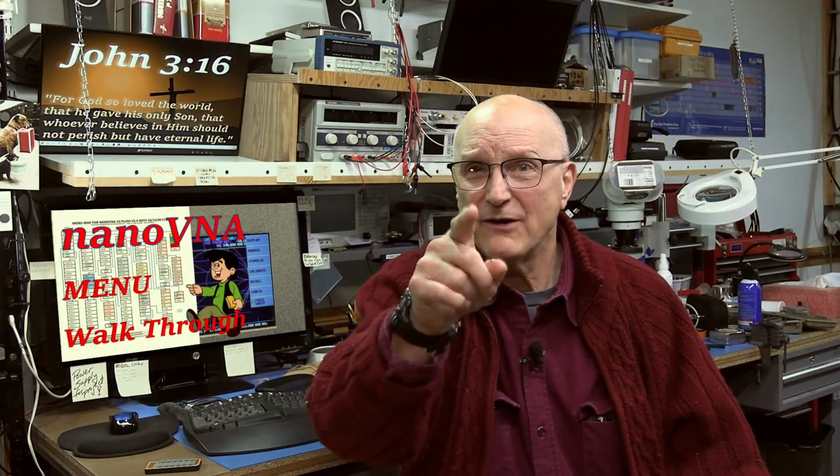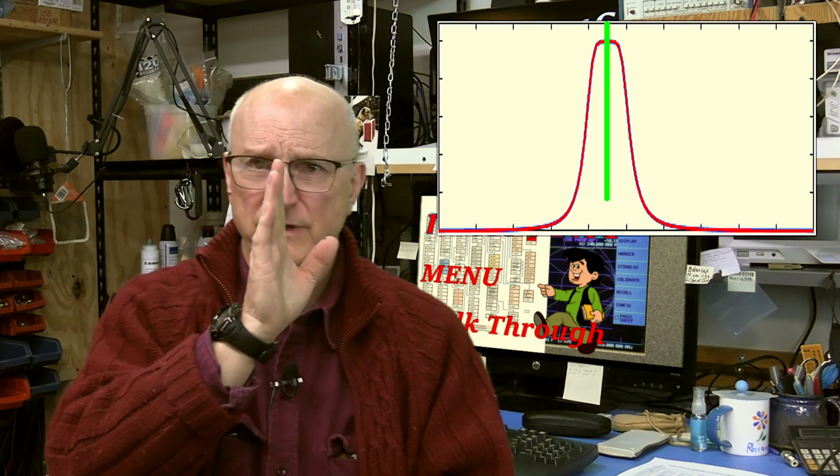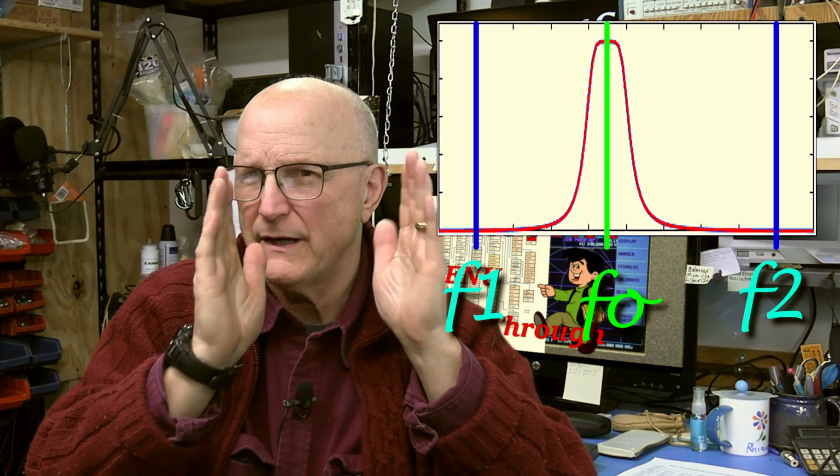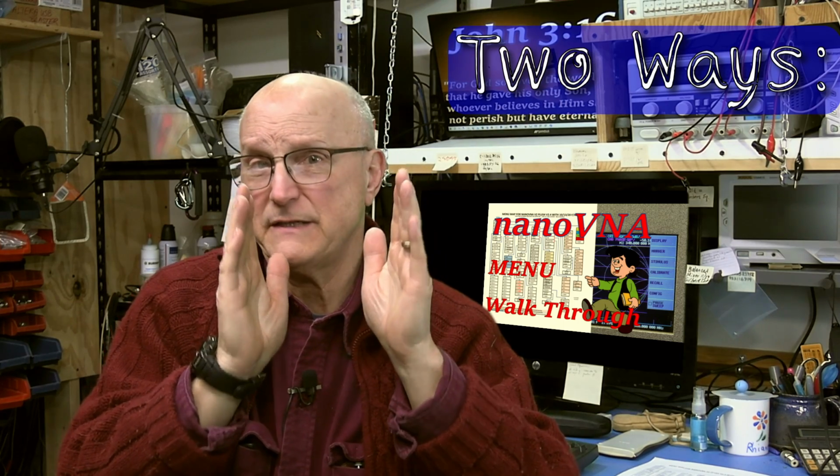But there's a second way to do this. So suppose that I wanted to test a bandpass filter. I know the center frequency of the filter, and I know the frequencies either side of this that I want to see the response for. Now, in a case like this, I would specify the test frequencies using the center frequency and span method. We start by specifying the span. Now, the span is the total width of the measurement from what will become the start frequency to what will become the stop frequency. Now, this can be specified in kilohertz, megahertz, or gigahertz.